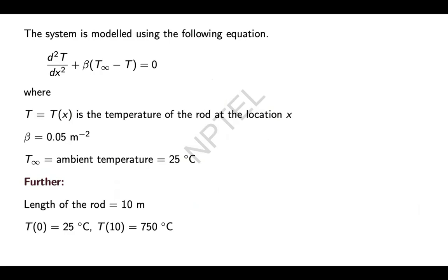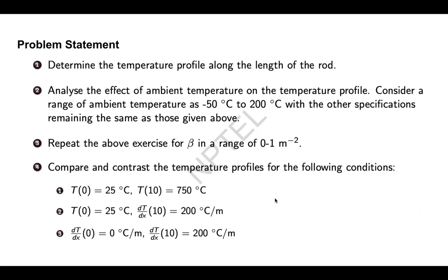Okay. Now let us look at the sub questions that are expected from us to solve. So these are the problem statements. Determine the temperature profile along the length of the road. This first part we already know. How do you get it? You have to directly solve the ODE equation. Then you will get, for different x values, the corresponding temperature T values. That is what you get as a solution when you use any kind of ODE solver in MATLAB. So that part is pretty much clear. Just that you need to carefully convert that second order ODE to a first order ODE. Then it's similar to what we have done in the previous classes.